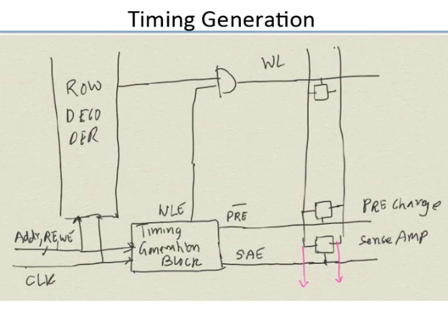It's similar to another concept called wave pipelining, where imagine you have a transmission line or a fiber optic cable with a long wire, and the latency of the wire could be nanoseconds, microseconds, etc. But you can send information at a much faster rate. The bits can be very small because the bits are all in transit. So it is like a wave, bits are flowing. Similarly, there is another way of doing pipelining called wave pipelining.